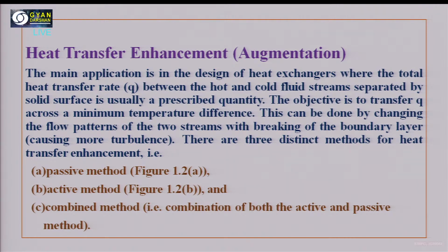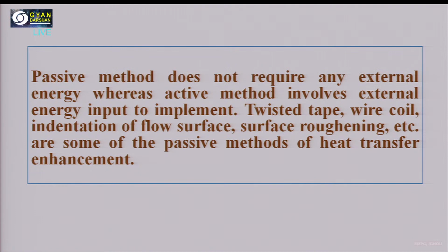If you want to enhance the heat transfer, there are different methods. One is the passive method, the other is the active method, and the third one is a combined method where we are using both the active and the passive method. So what happens in a passive method? In a passive method, we are not using any kind of external energy source. It does not require any external energy source, whereas the active method involves external energy input to implement.